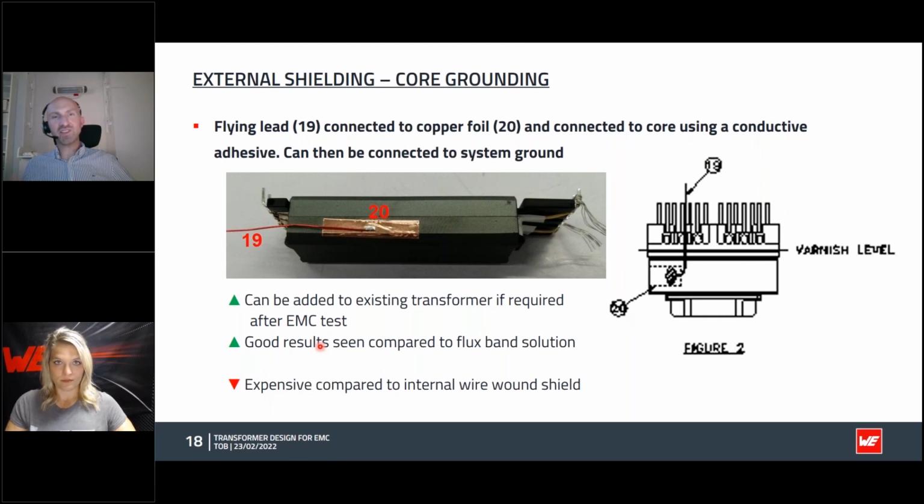But the primary to secondary interwinding capacitance is a big deal, because that's the main path for primary to secondary currents to flow. And so for EMC, it's far better to reduce that interwinding capacitance than the leakage, because leakage is a much easier phenomenon to deal with in filtering, whereas that capacitance is a broad spectrum problem.